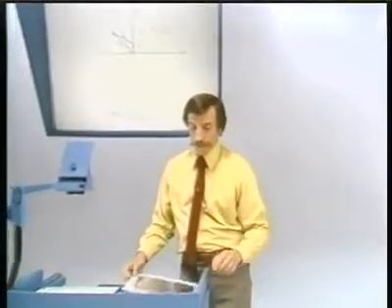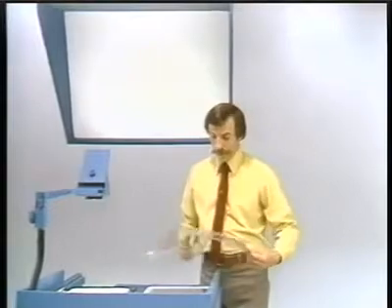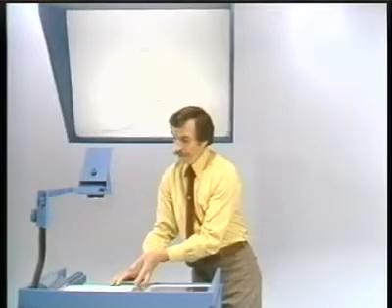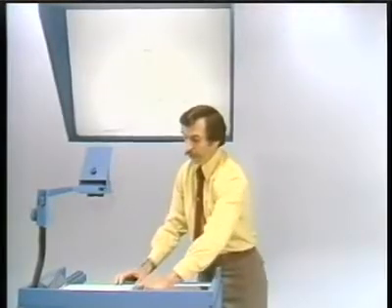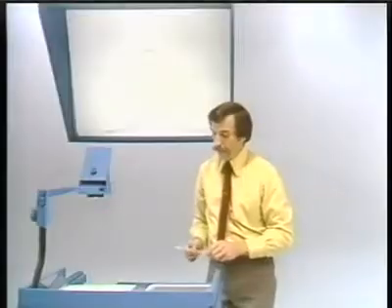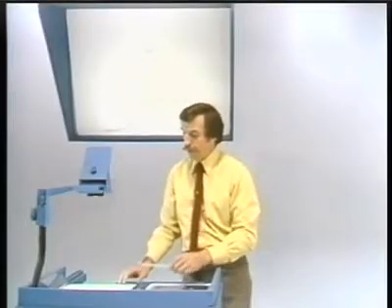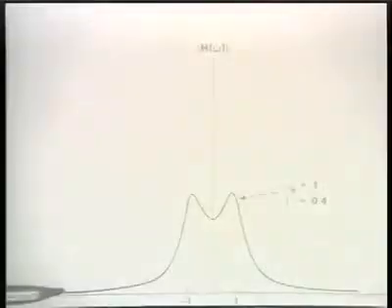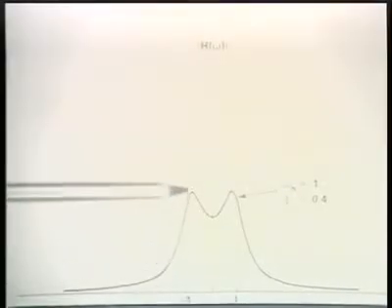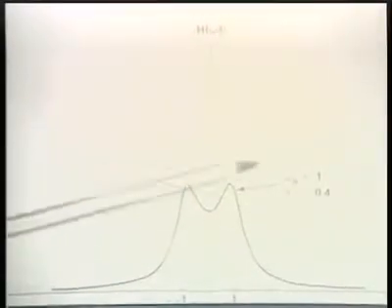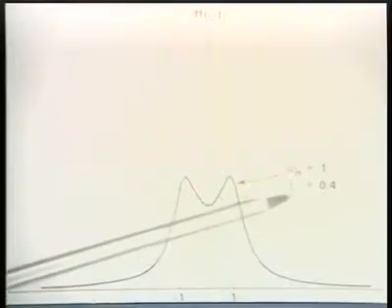Okay, so for complex poles then, for the second order system, what we see is that we get a resonant kind of behavior, and in particular then that resonant behavior tends to peak or get peakier as the value of zeta gets smaller. And here, just to remind you of what you saw, here is the frequency response with one particular choice of values.